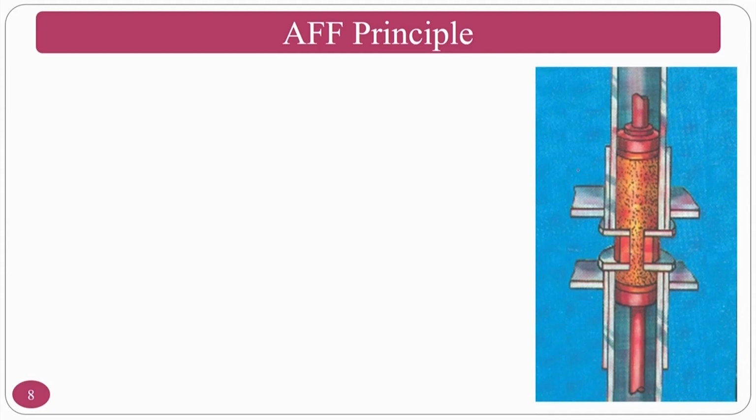You can see here the medium is placed in the top medium cylinder. This is the medium, and this is the upper medium cylinder, this is the lower medium cylinder. So, the medium has to be pushed to the lower medium cylinder across the workpiece. This is the workpiece. Okay. What will happen here is, the medium is reciprocated like this first, then comes back to the original position. This is the upper and lower hydraulic piston.